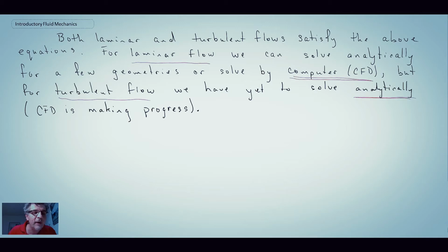And they came up with, using dimensional analysis and by doing a lot of experiments, a lot of deep insight into what's happening within a turbulent flow field. And that then became the basis of what we'll be using for determining the friction factor in turbulent pipe flow. So that's kind of where we're going with this. And what we're going to do, we're going to begin with looking at mean quantities in a turbulent flow. So if all you're interested in are the mean quantities, which is what we'd be interested in for the friction factor, then we're going to go through a bit of an analysis here, and I'll show you the statistics that come in with turbulent flow fields.